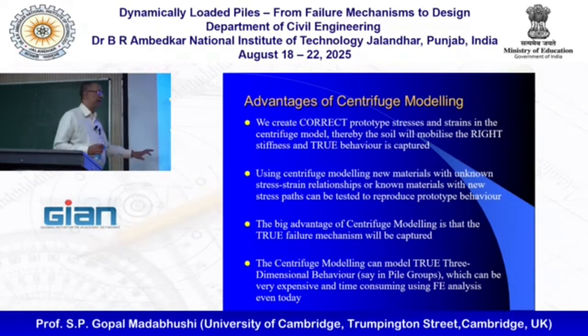The biggest advantage of centrifuge modeling is it will always capture the true failure mechanism. The rest of the course, the GYAN course, we are talking about how piles fail in liquefying soils. And the reason I'm so confident to offer a lecture course like that is because I'm confident that when we do these experiments, our centrifuge test will capture the right failure mechanism. And we are having great fun going through buckling of piles and the rest of it this morning.